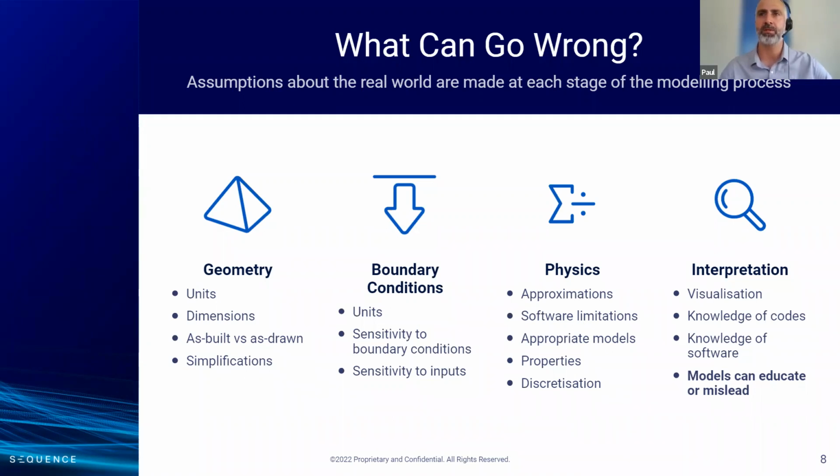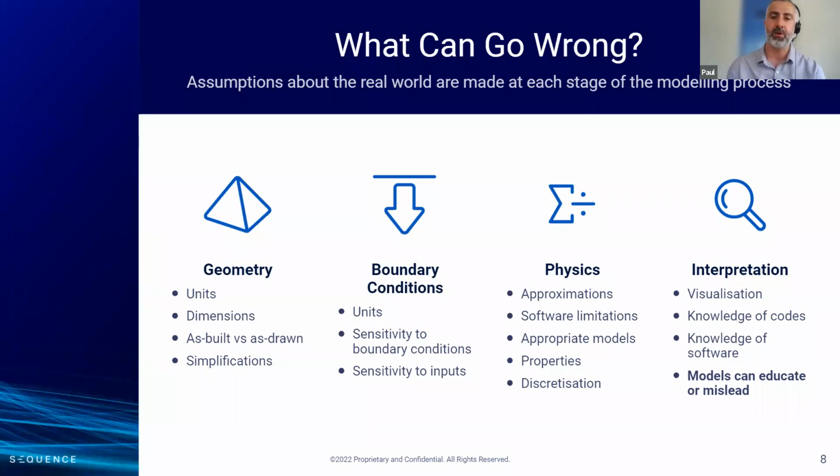So it's important to try and move through your model setup in a way where you're aware of what assumptions and limitations you're making. And also, I guess, understanding your software. All software has limitations in terms of physics. If you're using some entry-level software, CAD embedded stress analysis or fluid dynamics software can be very, very useful, but has limitations. And understanding where those limitations are is really important to building valid models that make sense.